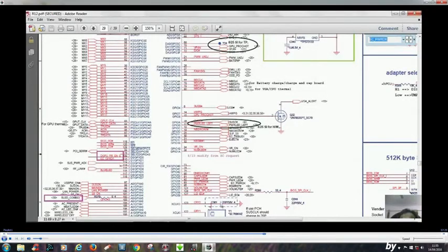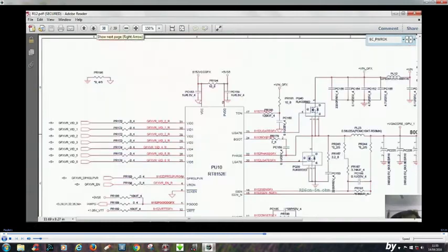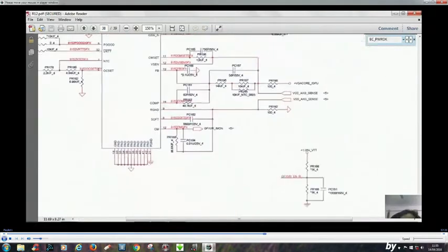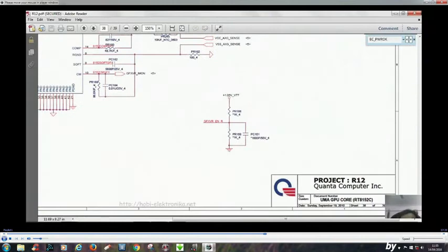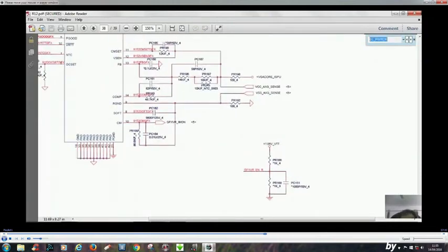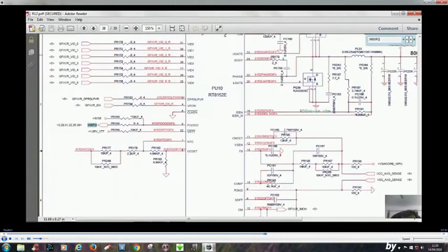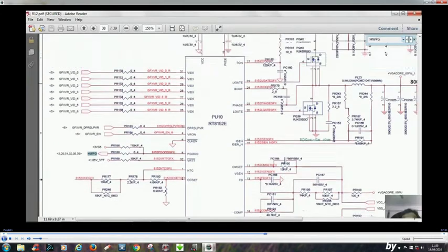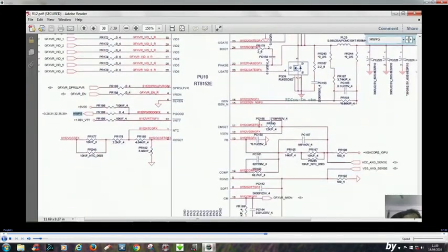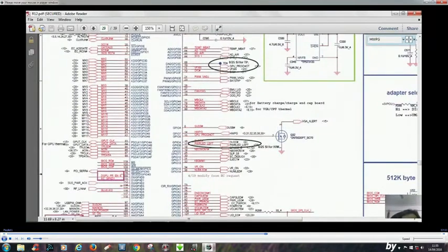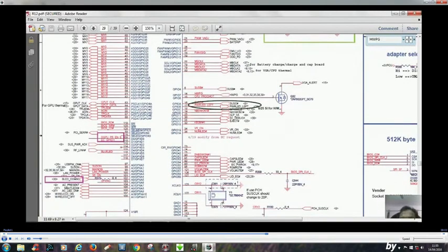Let's consider we go to page number 38. You can see all the regulators' power good, HWPG. All the regulators are generating this HWPG, and it is going to the IO controller, right? After the IO controller receives the hardware power good from all the regulators, it will generate EC power OK,